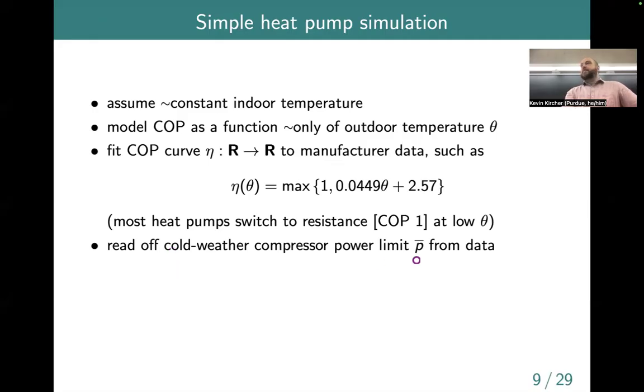And then in the simulations that you did for the homework that's due tomorrow, we have thermostatic control, and that imagines basically switching between the minimum and the maximum capacity for the heat pump. So to do that, you might specify an electric power capacity for the compressor, maybe on the order of 4 or 5 kilowatts for a typical residential application. Then you would take that P max, multiply it by eta, and that would give you the Q max, the maximum amount of heat that you can supply to the building, that shows up in the thermostatic control.